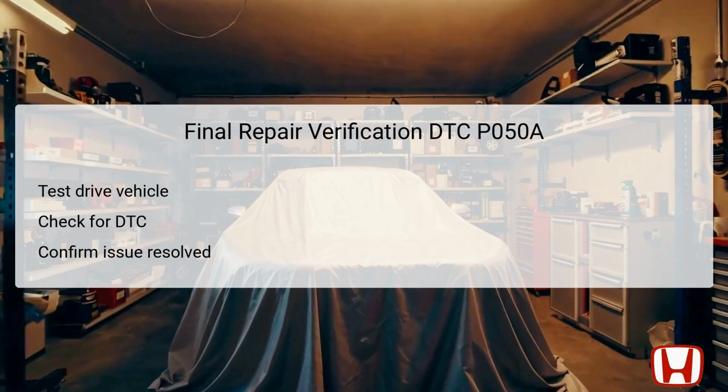Once the drive is complete, use the Honda Diagnostics System, HDS, to check for any stored DTCs. A successful verification will show that the P050A code no longer appears, confirming that the issue with the cold start idle air control system has been successfully addressed. This step concludes the troubleshooting process, ensuring that both functionality and diagnostics are in alignment.